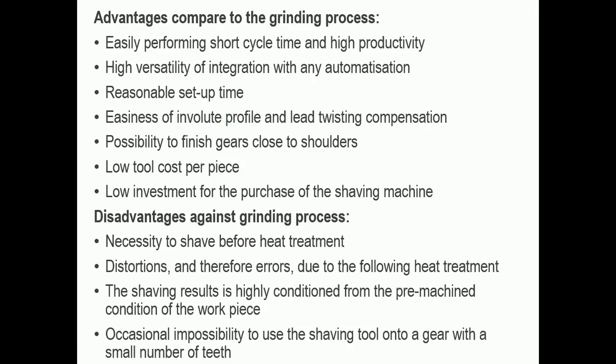What are the advantages of gear shaving? There are various advantages of the gear shaving process. Easily performed with short cycle times and high productivity, highly versatile machines, reasonable setup times, ease of input profile and lead testing compensations, possibility to finish gear close to shoulders, low tool cost per piece, and low investment for purchase of the shaving machines. Okay, what are the disadvantages?